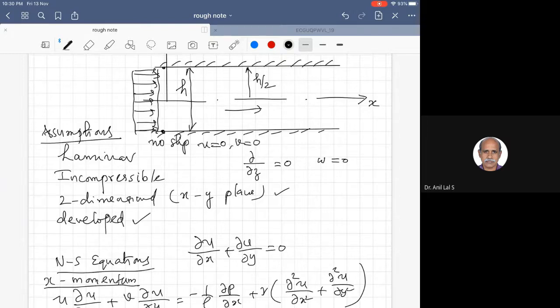So immediately, as soon as this fluid, which is having the average velocity, approaches the wall, and it is stopped in the direction of motion, naturally the fluid particle will be moving up. So there will be a certain amount of v velocity set in, and there is a reduction of u, but an increase of v from the inlet condition, where u is equal to some capital U average velocity and v is equal to 0. There will be a development of v velocity immediately inside the channel. So the resultant velocity will be something like this.